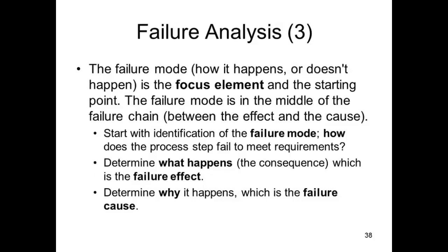Start with identification of the failure mode. How does the process step fail to meet the requirements? The worker forgets to check the torque. Determine what happens, which is the consequence. Determine why it happens, which is the failure cause.